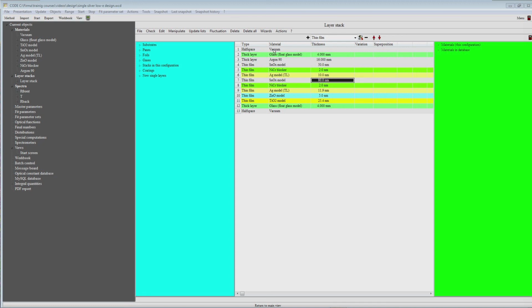So on top here we have the outside air, we have the glass, then the gas and the coating and another glass. So it would be good to bring the coating upwards so that it's underneath the top glass layer. And we can just reverse the stack here by a lot of mouse operations, using clicks on these arrow buttons.